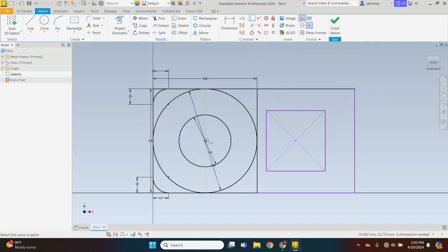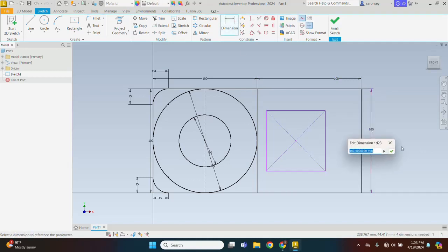And those two circles are also fully defined. So let's apply some dimensions to the sketch on the right side. So the dimension command again, let's specify the length of this line. So we click on that line, we drag to the top, and we can change the dimension to 100. We press enter. Let's do the same for this vertical line. So we click and then we drag, 100. Okay, that is fine. So we just straight away click again and then okay.